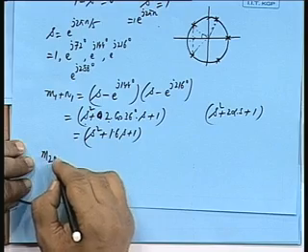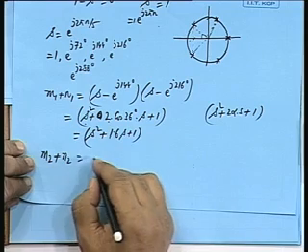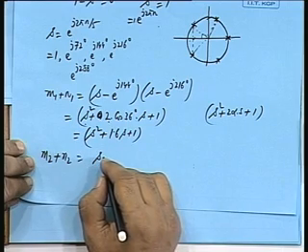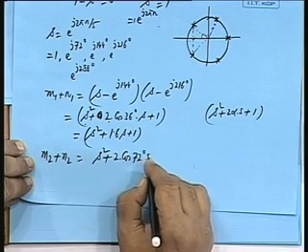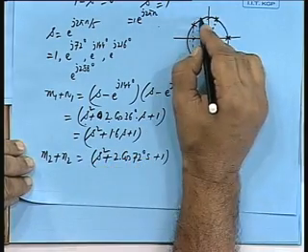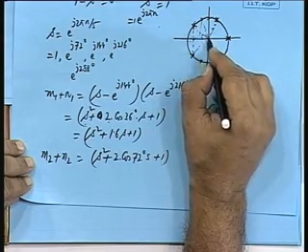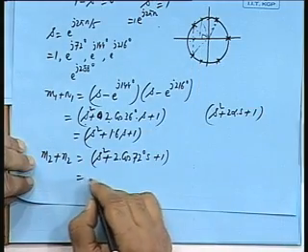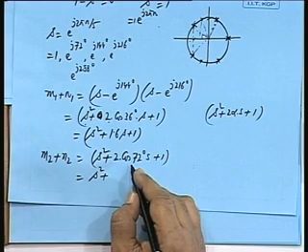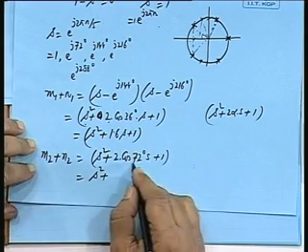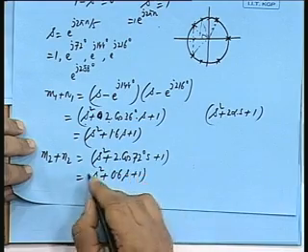M2 minus N2, you know, so M2 plus N2 will be, this is 72 degrees. So, s squared plus 2 into cosine 72 degrees into s plus 1, straight away images of these will be on this side, alright. So, the real part of this will be cosine 72 degrees, s squared cosine 72 degrees, and cosine 72 degrees is approximately 0.3. So, 2 into 0.3, so 0.6 s plus 1.